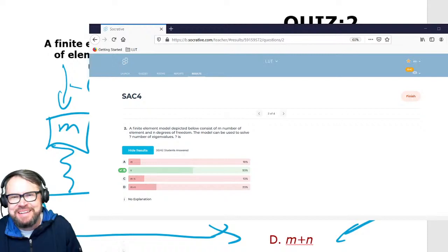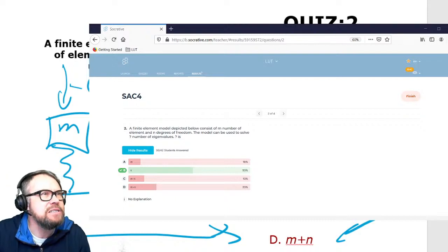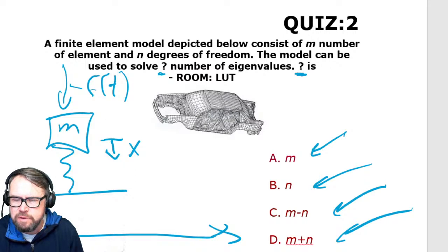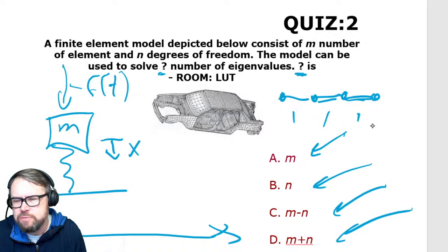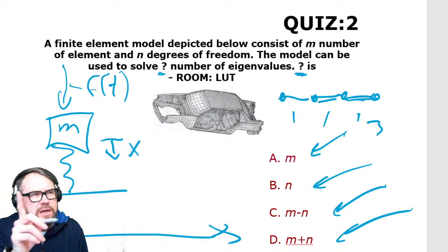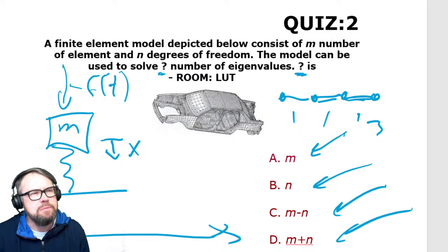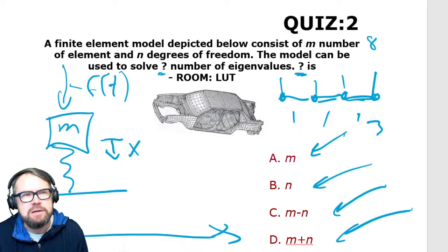Okay, so I'm done. So let me take this away. All right. If I have, again, this cantilever beam, or let's say that I just have a beam structure like this, a beam structure that consists of 3 elements and 4 nodes. The 4 nodes and the nodal degrees of freedom associated with this nodal location, that's what really defines my size of the problem. Let's say that each has 2 degrees of freedom, so it will be 8 degrees of freedom.